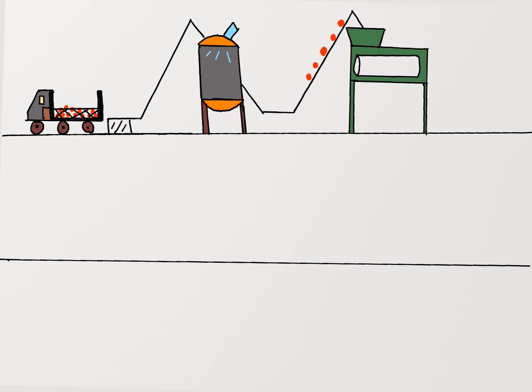Commonly used stripper is a drum stripper, which has a long horizontal cylindrical drum that is rotated fast enough to lift the stalks using centrifugal force. The inner lining of the drum is fitted with T-bars that are spaced just enough for the fruit to pass through, leaving behind the stalk. This process separates the sterilized fruit from the bunch stalks.